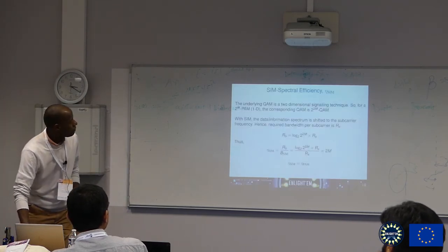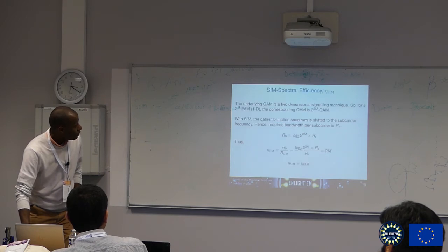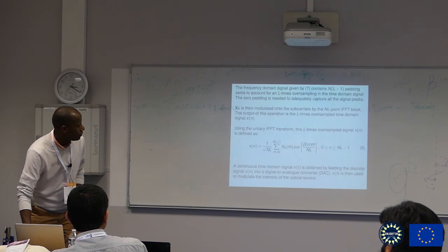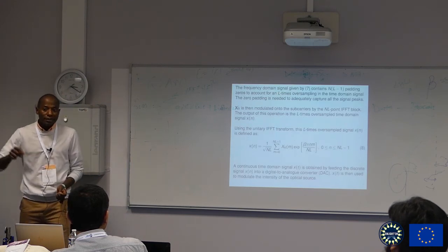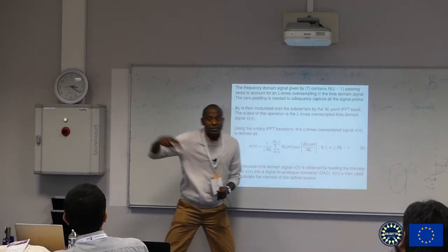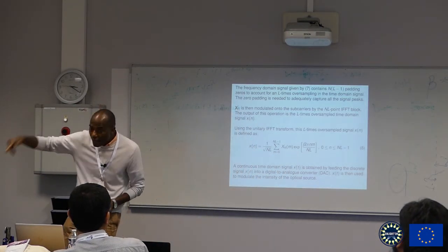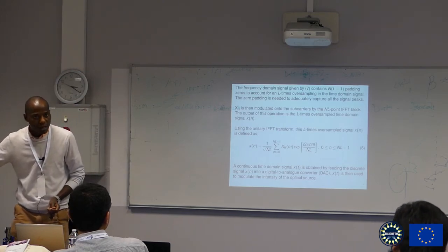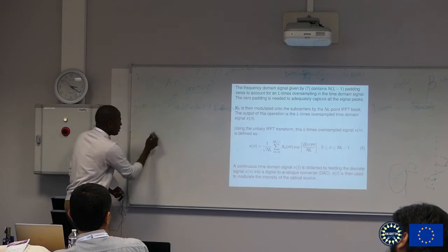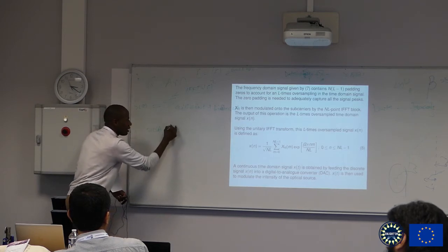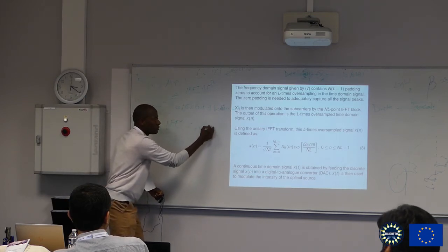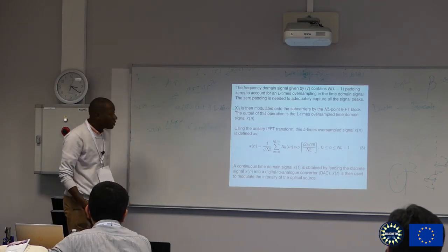And you can see I've put some examples there of how to find the spectral efficiency for OFDM. That's one thing I really have to mention here for OFDM. Normally when you do this operation, IFFT, the output is complex, right? But we can take advantage of the symmetry of IFFT, called the Hermitian symmetry. Basically, if you've got X(t), and you do IFFT of this, you get a complex output.